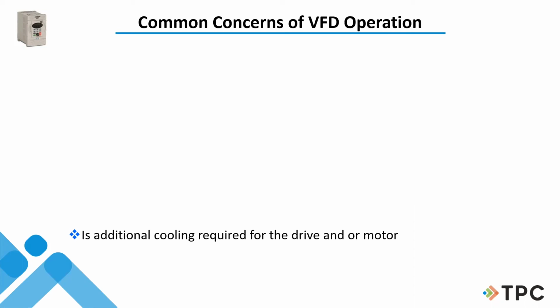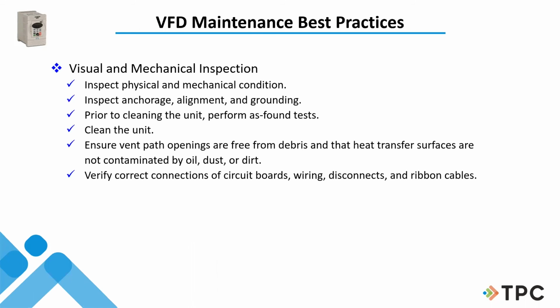Cooling required for drive and or motor. So back to what I said, when you're going to put that drive in a cabinet, how are you going to cool it? How are we going to dissipate the heat? And same way with the motor, we said when it's going slow, we need to make sure we have an external cooling fan on there so that we can dissipate some of that heat because the fan's turning so slow. So just some things to think about. There's a ton of things to think about, guys. All I tell you is that this is a short amount of time to give you a lot of information about drives, but obviously that's why we have a couple drive classes.